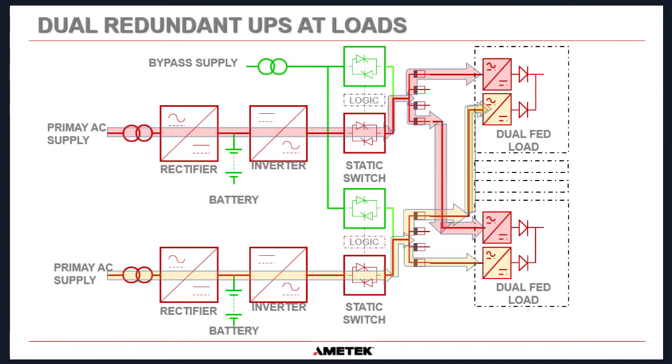Okay, now in a lot of systems, the UPS is supplying the DCS for a control room, so the distributed control system for a control room. Okay, now modern technology knows that you're going to be using UPS systems to power their DCS, and what most DCS manufacturers do now is they allow you to have multiple AC inputs to their DCS system.